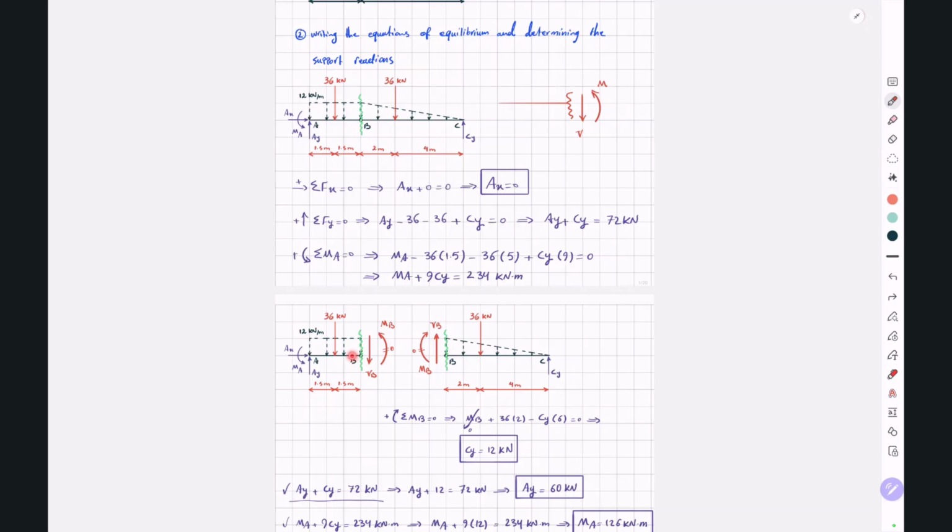You will have two cut segments when you cut the beam, and by taking the moments around the point where you have your internal hinge, and using the fact that your internal moment at that point is equal to 0, you will be able to write an additional equation. Using that additional equation and the other equations of equilibrium you wrote for your entire beam, you will be able to determine your support reactions by solving a system of n equations and n unknowns.